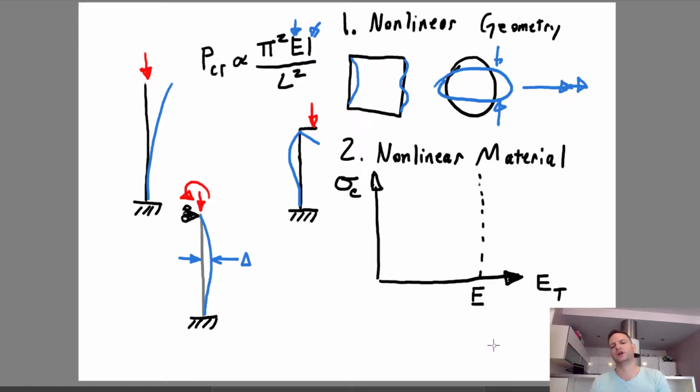If you go online to MatWeb, or look at the MMPDS, or whatever reference handbook you've got, they usually show this modulus E as the critical value that they give you. They don't give you much more than that. Sometimes you get lucky and they have some curves for tangent modulus, but not always. So you use this value of E and you assume it doesn't change.